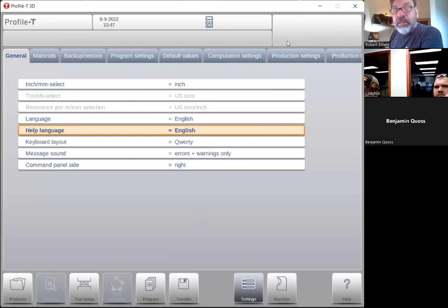I look at that specifically to see status or state, because I want to see: is the light guard upsetting the machine? If you have a light guard on this machine and the light guard gets upset, it will not pass the foot pedal signal on to the control. You'll step on the pedal and nothing happens, and you're always thinking it's the control's fault. That's where it'll show us what's wrong.